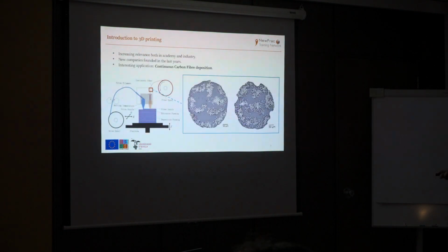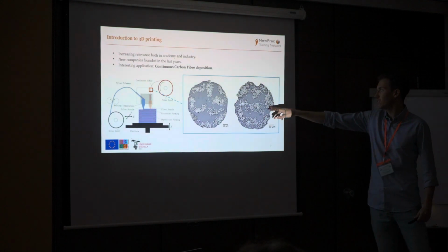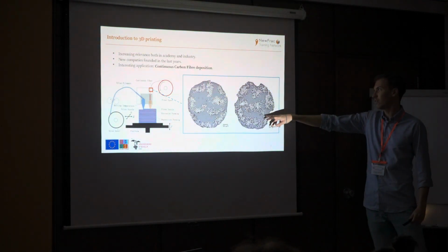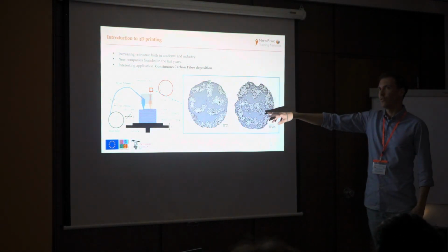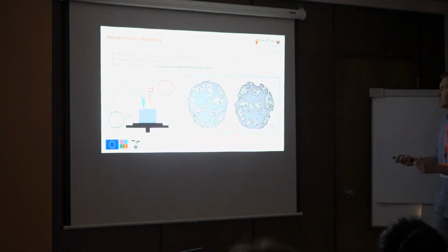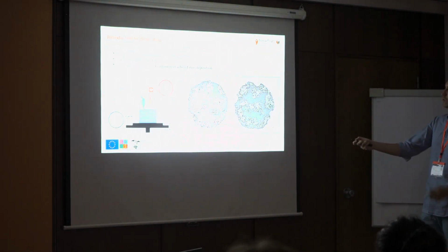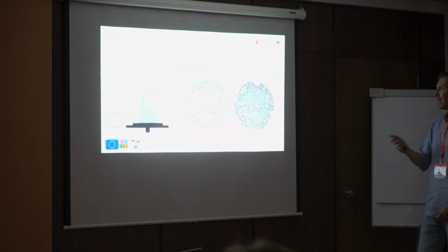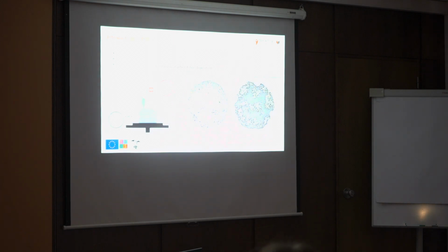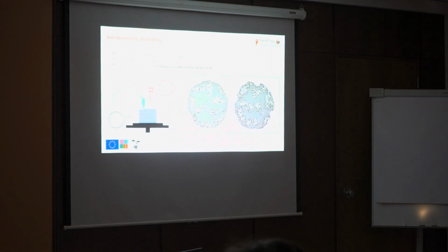Also, some problems in this kind of structure are that here, maybe you don't see, but there are some voids. Here there is no fiber nor polymer. You can see the black zone is where there's nothing, basically. It's a hole, and this could lead to some troubles when dealing with the material parameters.